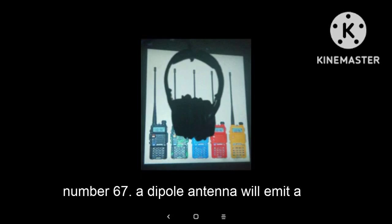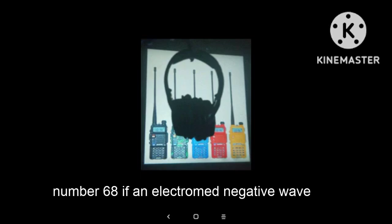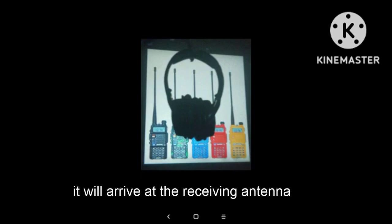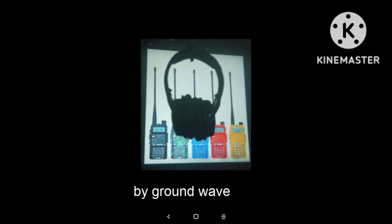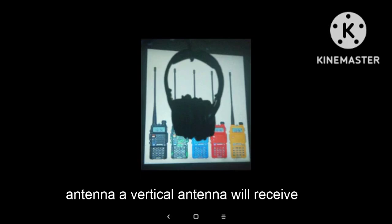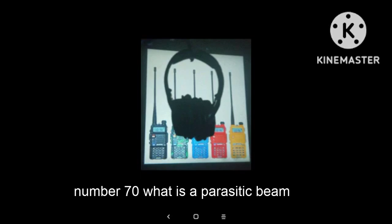Number 67. A dipole antenna will emit a vertically polarized wave if it is mounted vertically. Number 68. If an electromagnetic wave leaves an antenna vertically polarized, it will arrive at the receiving antenna by ground wave vertically polarized. Number 69. Compared with a horizontal antenna, a vertical antenna will receive a vertically polarized radio wave at a greater strength.